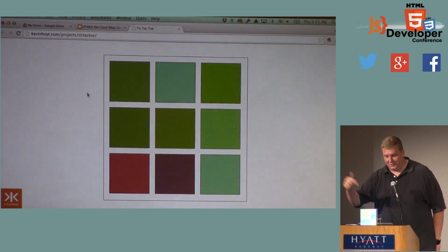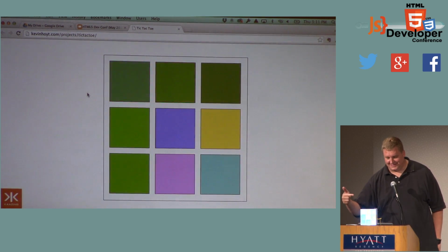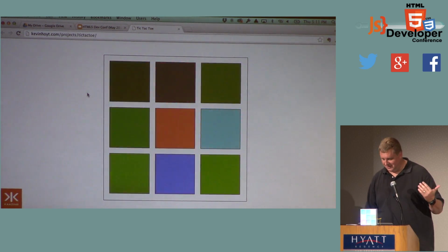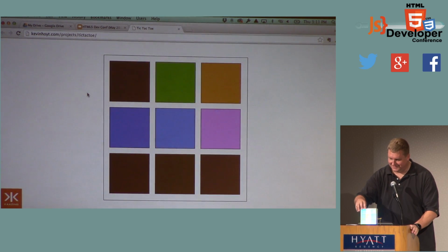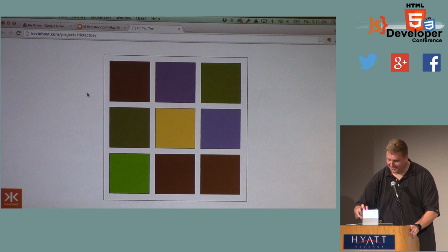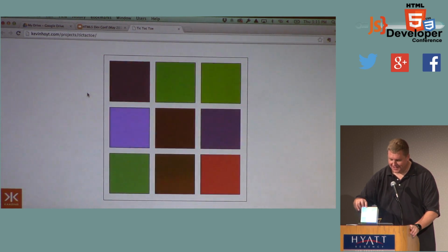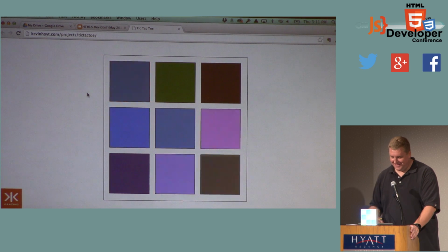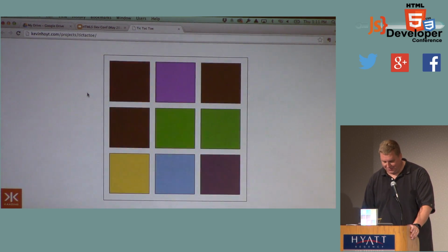All thanks to an Arduino Yun in there. It's got those RGB LEDs in there. It's effectively listening in a WebSocket real-time solution to produce those colors. Nice. I wrote that STOMP implementation from scratch for the Arduino Yun, so there were no libraries for it. So glad to see it held up.